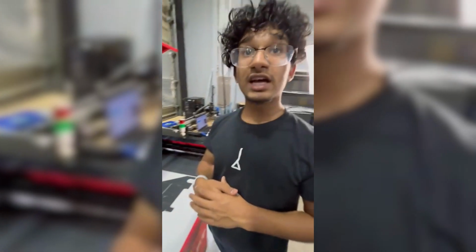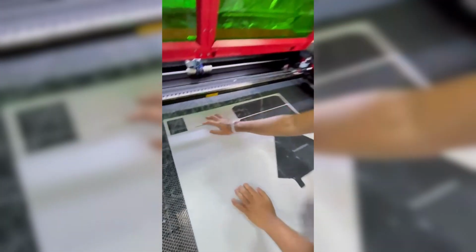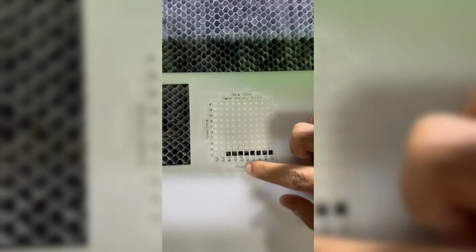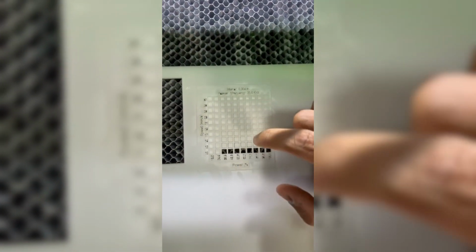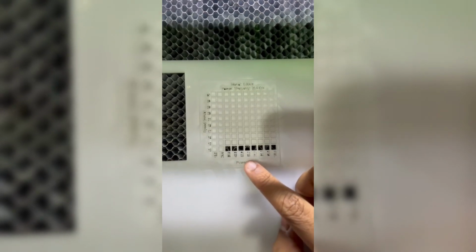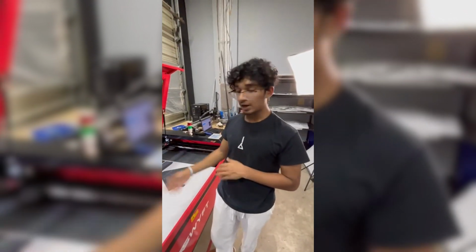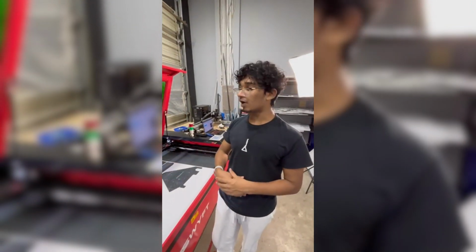So following the material test, we're able to see that here, we're going to look for the middle spot to see where you want to cut it. And you can see that it has 10 here and 50 right here. So we're going to want to have something in between the 50 and 60 to where we want to cut it. So we have our laser cutter set to 10 and 50, and that's what works well for us. But for different materials and for everything you want, you're going to have to rerun this material test and run it for every material.